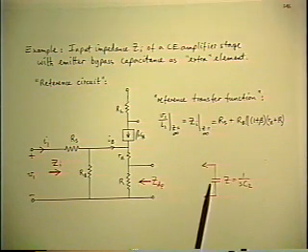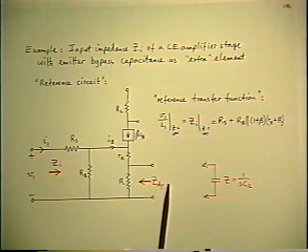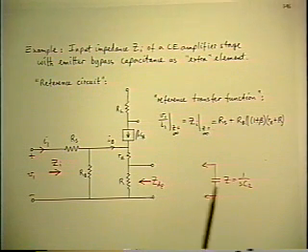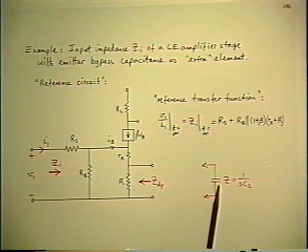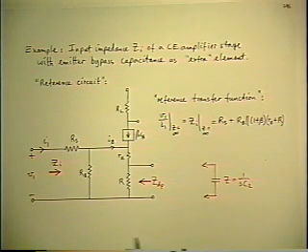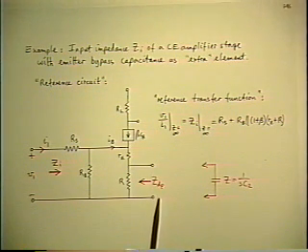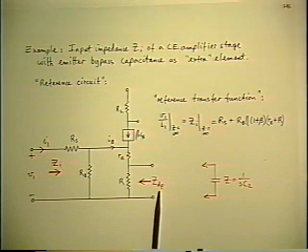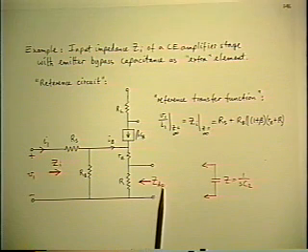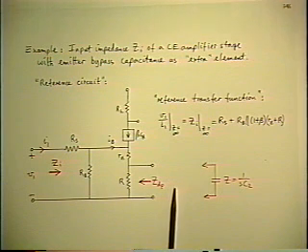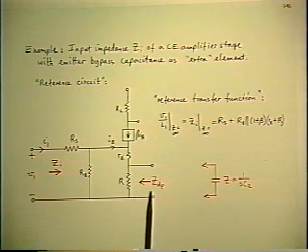But in order to do that, we have to calculate two driving point impedances. So I've simply represented that as the ZDP looking in at the terminals where the capacitor is going to go. Okay, we have two calculations to make. The first one is we apply a second independent source across these two terminals, and I'm not going to bother drawing that this time either. I've done that enough times using Thevenin's, Norton's, or an unspecified source. Every time I've been saying it doesn't matter what the source is. So now I'm not even going to draw it at all. You just imagine that it's there. So there's a source driving into those two terminals.